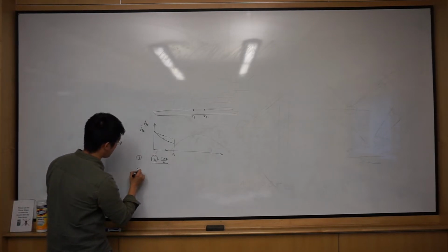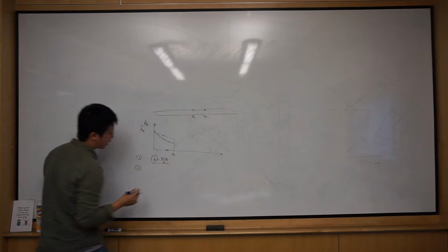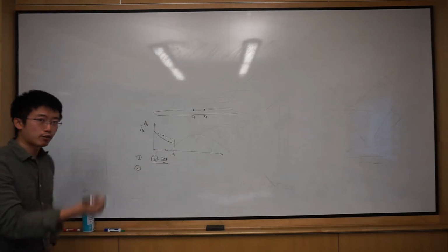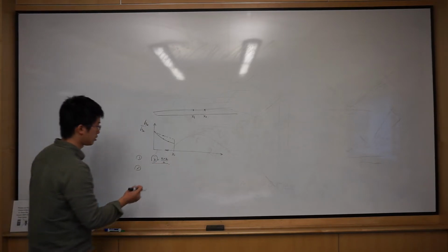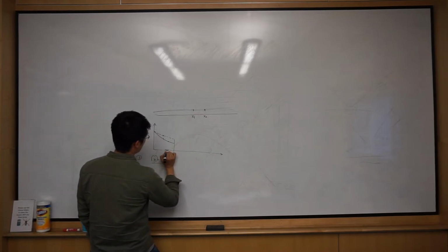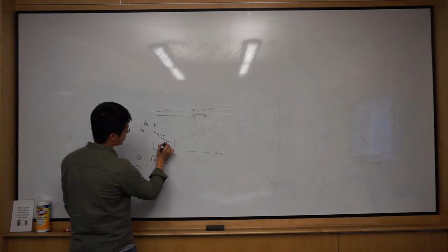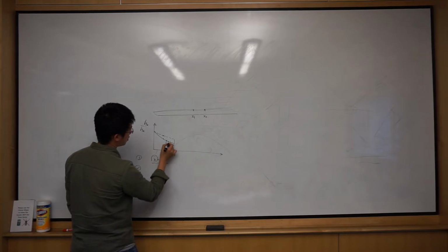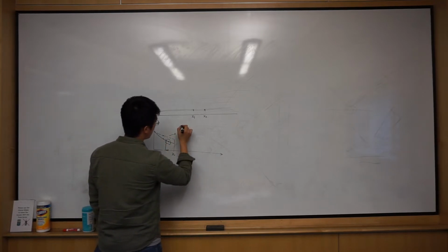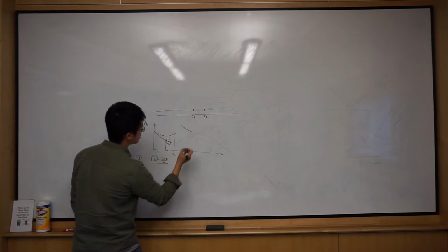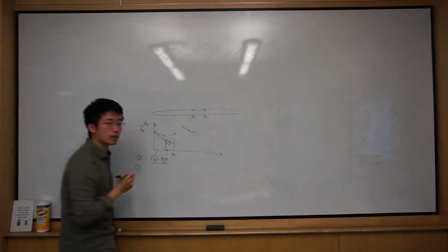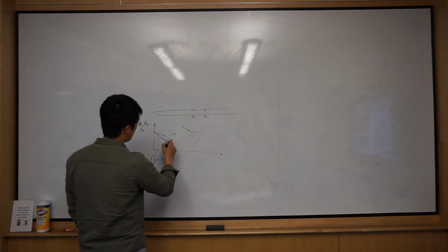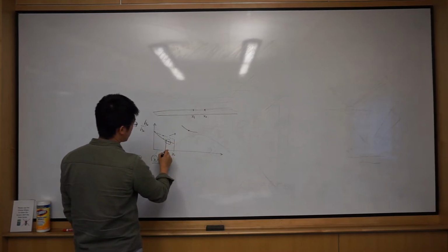The second idea is saying, let's try the average of the local convection coefficients. The local convection coefficient at x1 is here, the other one is here. Then we look at the average of these two values. If I zoom in, one is saying I want to use this number as the average of this segment.